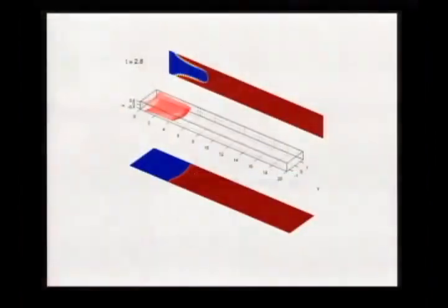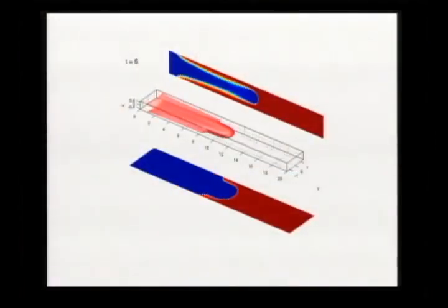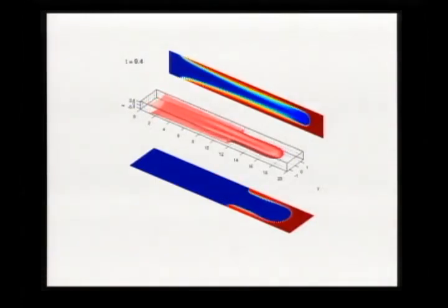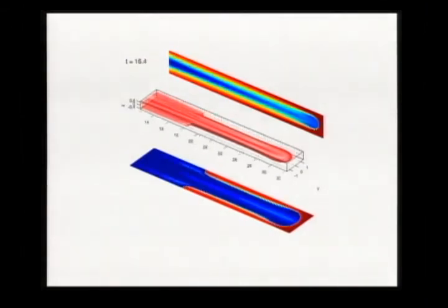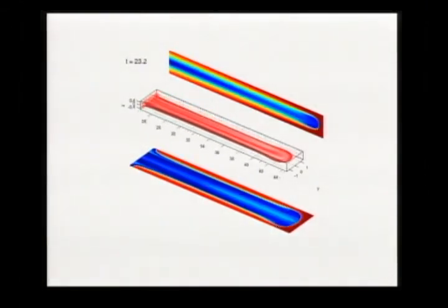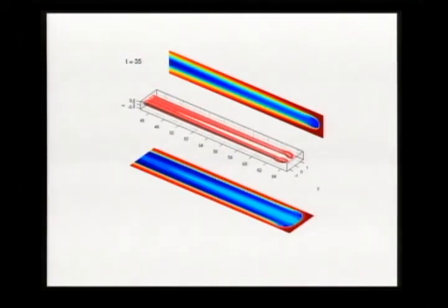This is our first simulation with Peclet number 1000 and viscosity ratio in exponential scale 3. As expected, a smooth diffusive finger grows, but as the projections of the symmetry planes indicate, something is going on inside the finger, and that's exactly the inner splitting that I had mentioned previously.